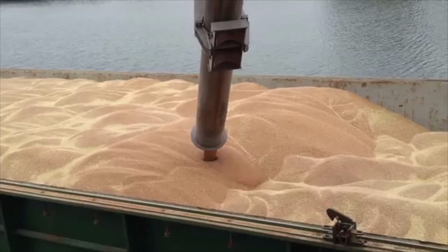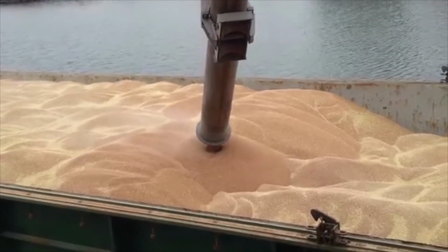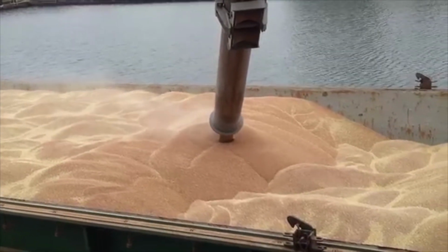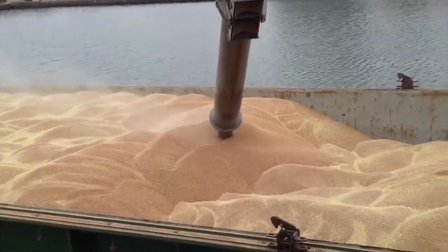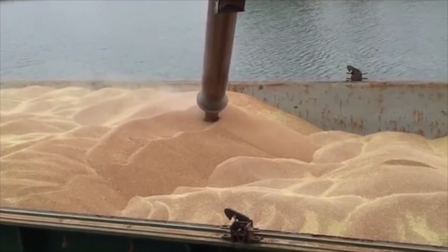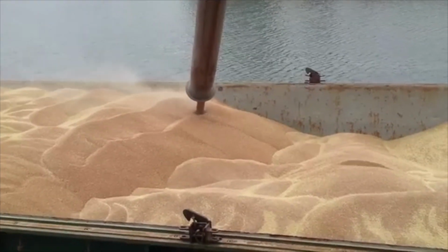To avoid shifting of cargo, the grain surfaces must be reasonably trimmed. The cargo should be trimmed so that all spaces under deck and hatch covers are filled to the fullest extent possible. When untrimmed, the cargo should be trimmed within the hatchway but may be left at its natural angle of repose on the surrounding area of the hatchway.